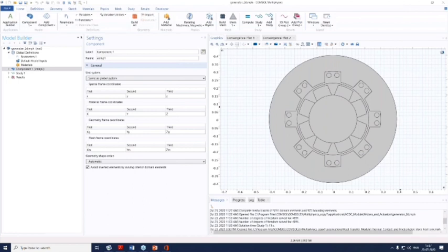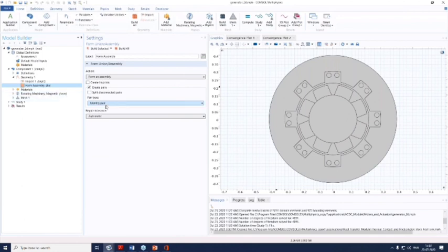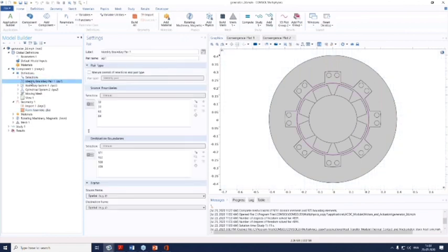How to assign? Okay, my colleague Nitish has already answered how to assign identity pairs in the form assembly node. While creating the form assembly itself, you will see that for the pair type you can click identity pairs, and once that is done, based upon how the geometry is created, the identity pair will get created.